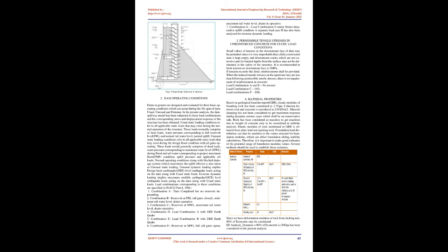A separate analysis shall be carried out for the forces in valley direction, across river flow, to evaluate high stress zones in the dam. The reinforcement shall then be computed where tensile stresses exceed permissible limits. Permissible tensile stresses are mentioned later in the report.